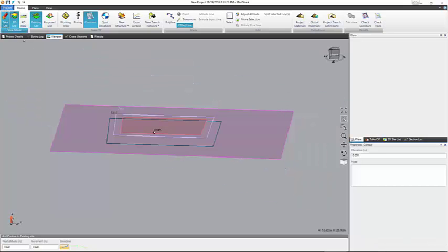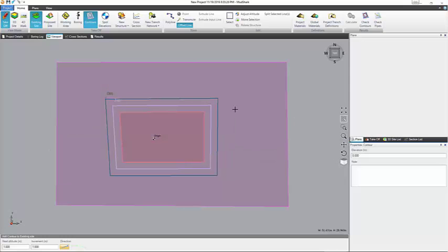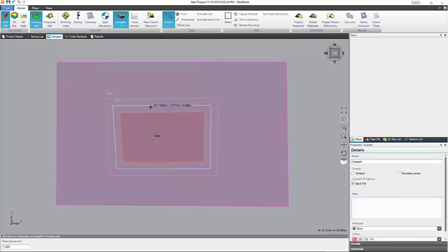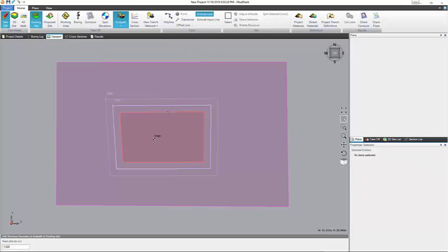Okay, let's go to take off view and then to top down. Okay, so then let's say we want to put a footpath around the building that's half a meter off from the edge. What we can do is go in extrude line. Now what this does is it extrudes the selected line by the distance you give.